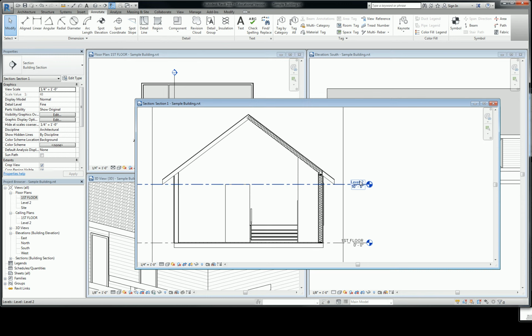I guess the answer to that is yes. You do have to still make all of your wall types, but like I said before, when you get into an office somewhere, they've already got them all made pretty much. If you're just working on Type 2B commercial structures, you've got all of your CMU backup walls and concrete with metal deck floor assemblies all pre-built for the most part. So all you might have to do is adjust one a little bit and make a duplicate. That's the general position of most templates. Does that make sense?